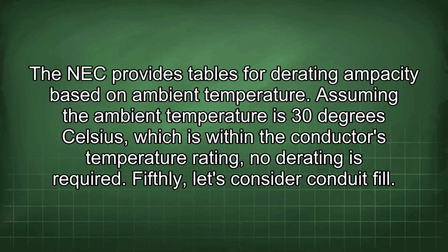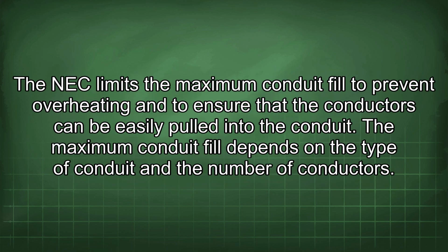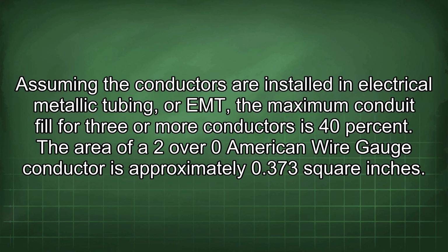Fifthly, let's consider conduit fill. The NEC limits the maximum conduit fill to prevent overheating and to ensure that the conductors can be easily pulled into the conduit. The maximum conduit fill depends on the type of conduit and the number of conductors. Assuming the conductors are installed in electrical metallic tubing, or EMT, the maximum conduit fill for 3 or more conductors is 40%. The area of a 2/0 American wire gauge conductor is approximately